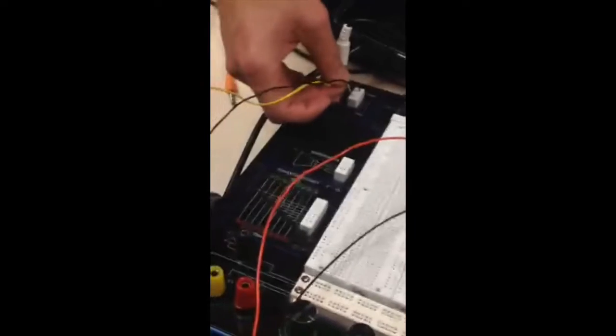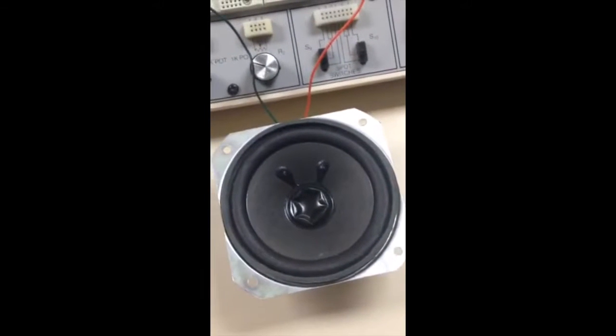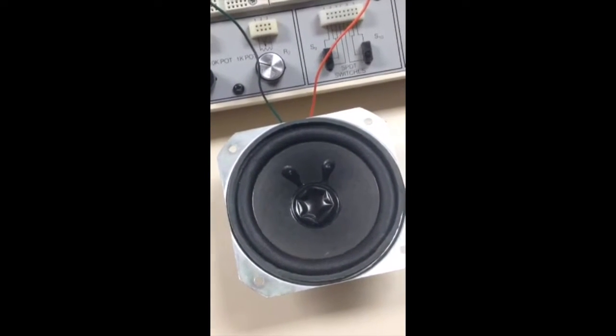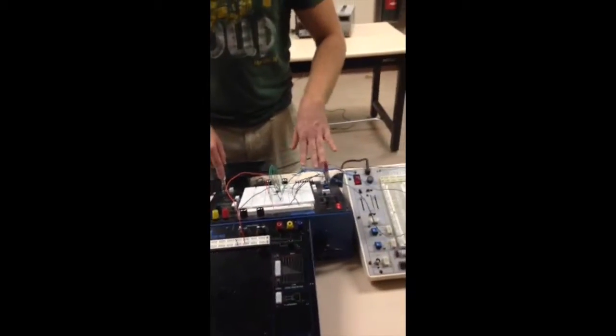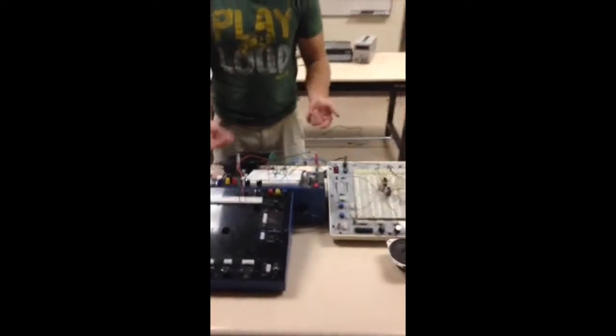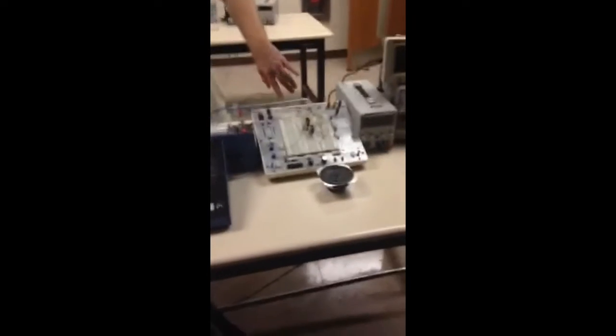So this is the speaker after it's gone through the low pass third order Butterworth filter and amplified with the push-pull. And this speaker is directly from the source. We're using a phone, which is a 1.1 volt auxiliary port. So you can see we have it split here between the two AC inputs. This one is for the Butterworth, which goes to the filter and is amplified, and this is just straight in. And as you can hear already, that's just straight bass. Anything lower than 100 hertz is being pushed through, and just at that point it's quiet.